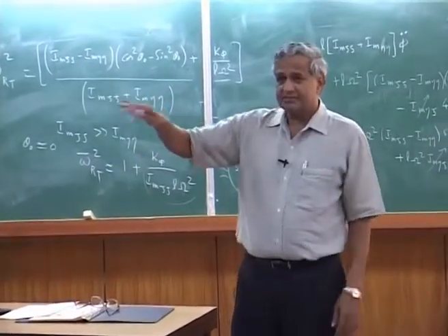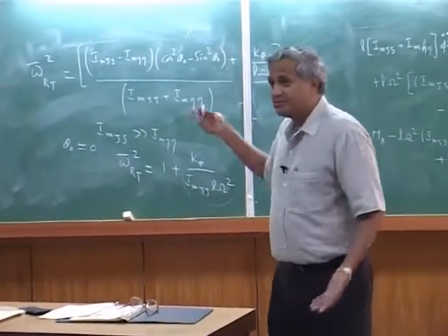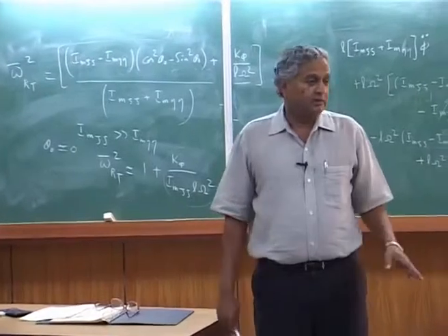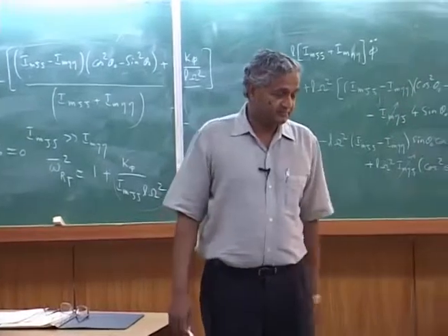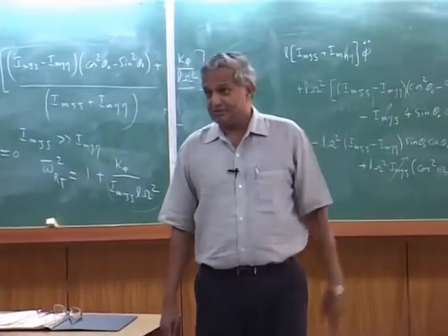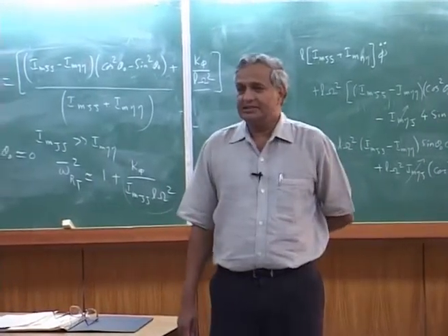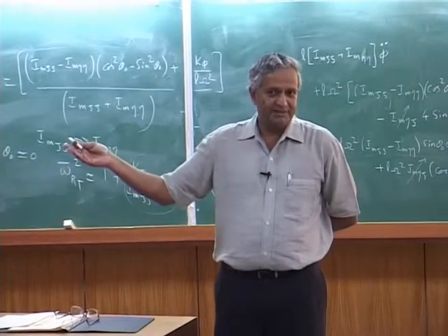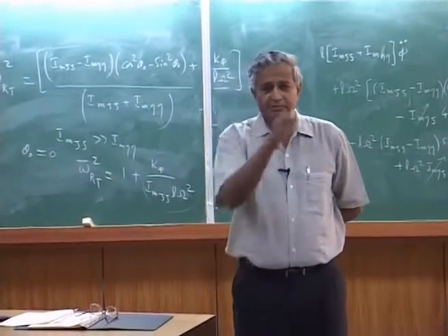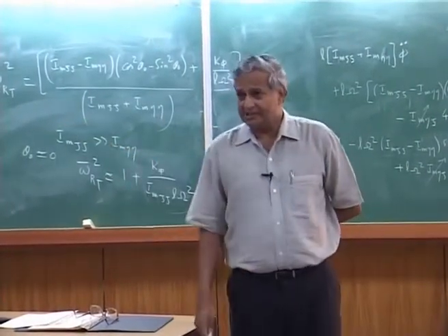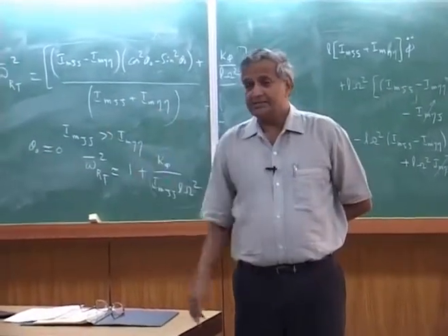Only thing is, what is the effect of the centrifugal load in flap motion you consider, lead lag motion you consider, torsional motion you consider. But if you say, no, I want to include elastic deformation in the axial direction, then you write the axial equation. Then there are certain approximations made, which is usually what you normally make in traditional bending problems. What do you do? You draw a line, a reference line, and then it deforms. You see the length of that line does not change.